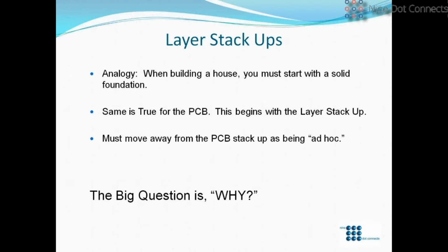Okay, so it's like a house. We can't just build a house ad hoc. Some people can do it, but the fact of the matter is, if you're going to build a house, you really have to build something that has a design, a plan, an architecture to it. And in the PCB world, it's really no different, especially in the high RF microwave range, and that is the layer stack up. So we have to move away from this ad hoc method of, I'll deal with the layer stack up later. We've got to actually deal with it before we even push the net list over to the PCB side. And the big question is why?